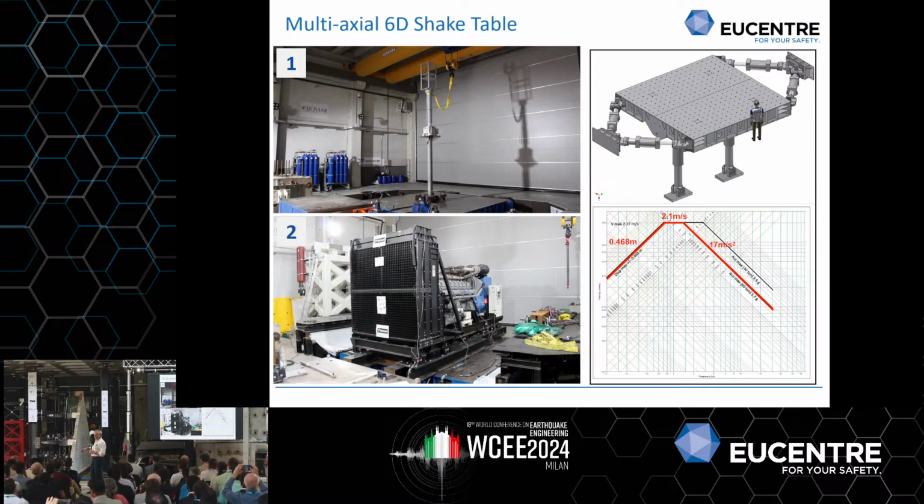Under the shake table there are 4 pancakes that can only push, they cannot pull. The shake table is moving on top of these pancakes. Then there are 2 spring actuators. Before testing, like now, the spring actuators are pulling down the table so that the pancakes are halfway in, so that they can then control the lower shake table in this way. So 6 degrees of freedom.